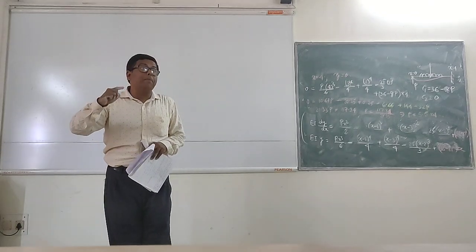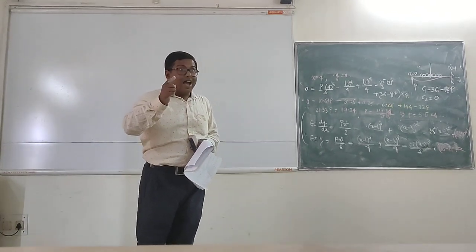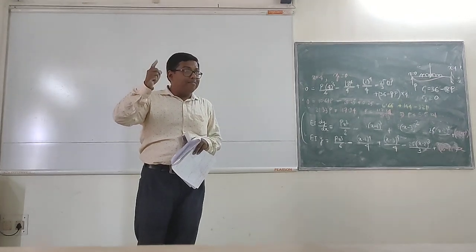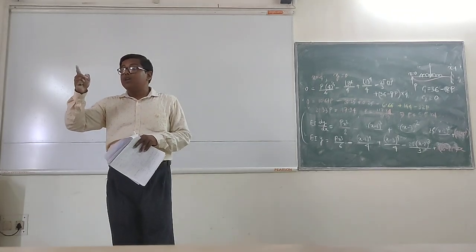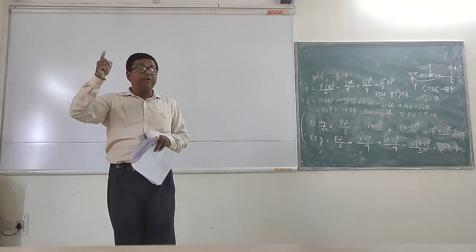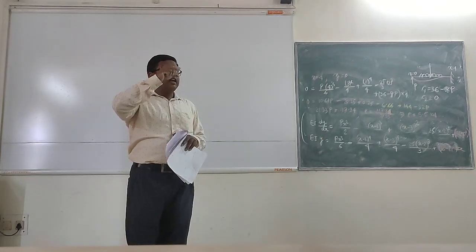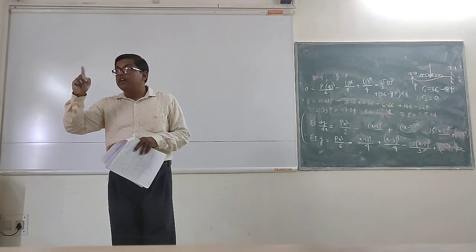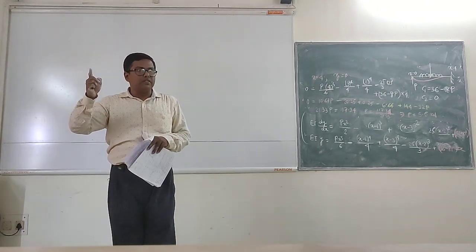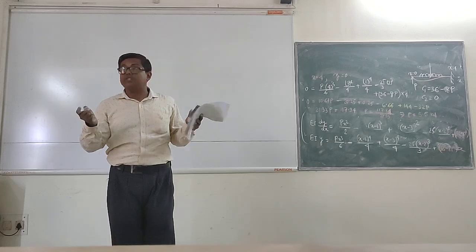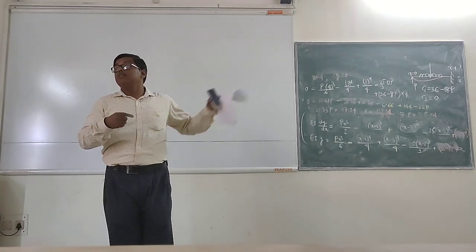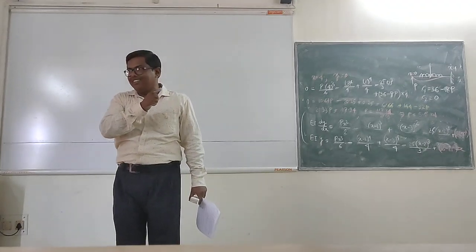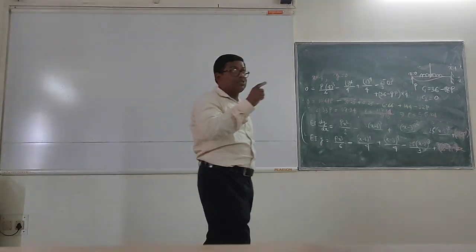All these methods will come into picture. So using any of the methods, you can find out the deflection, and then if you apply the compatibility condition at a particular point, you should be able to find out the indeterminate reaction component, which in structural mechanics terms are called redundants. What are they called? Redundant. So redundant forces, which you cannot find out using the equations of statics, you can find out using the deflection conditions. So this is the applicability of deflection finding in structural analysis or in case of beams.